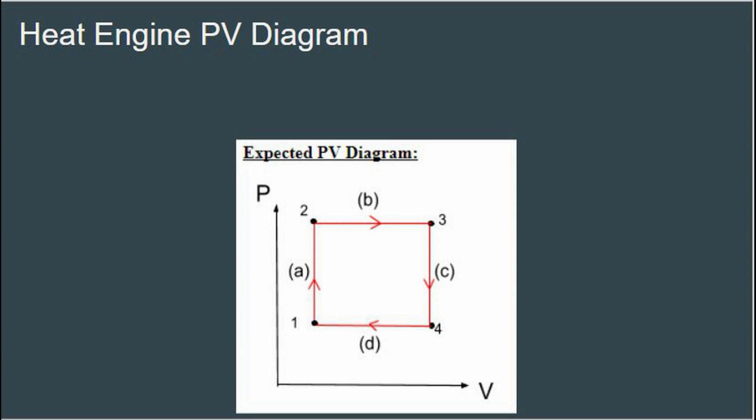Once placed into the hot bath, the temperature of the cylinder will rise until the pressure is large enough to overcome the weight of the piston and the pressure from the atmosphere. At that point, the piston will rise. Something to note is this process is isochoric, meaning the volume is constant and will not change until there is enough pressure, or it reaches a certain threshold that will allow the piston to move.